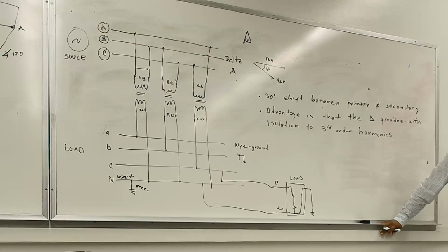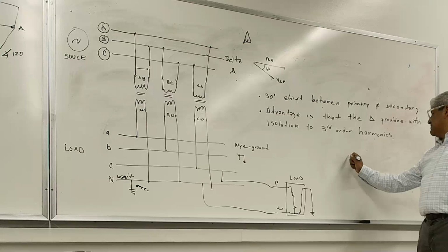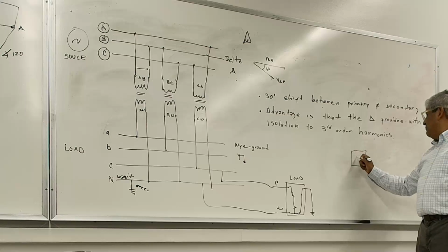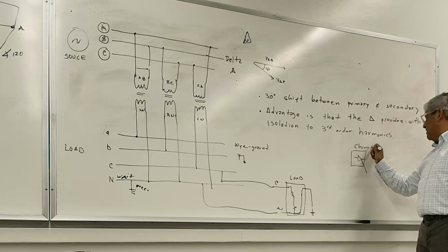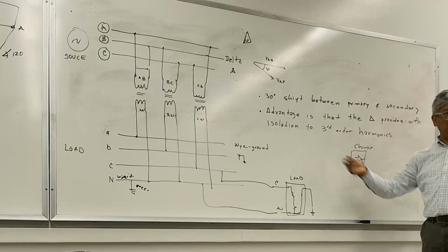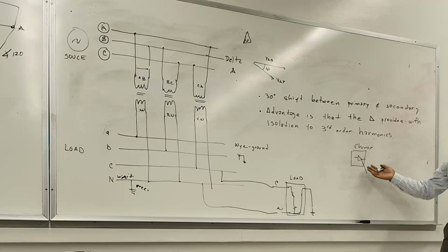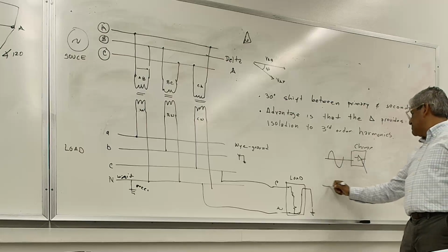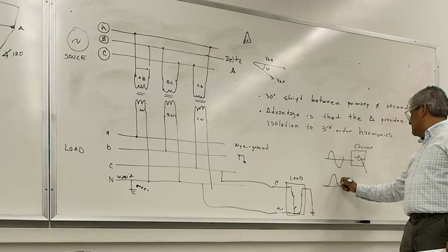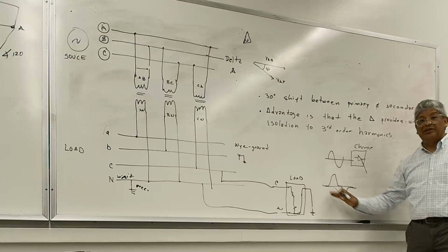When you say third order harmonics, you're talking about like switching loads that affect the source, right? Correct. Non-linear loads can be, say, a charger, a good example, like a battery charger for either vehicles or batteries. Or if you have a solar PV plant, you have a rectifier, so you have what we call non-linear loads, because they do not consume current like this, but most likely something like this.